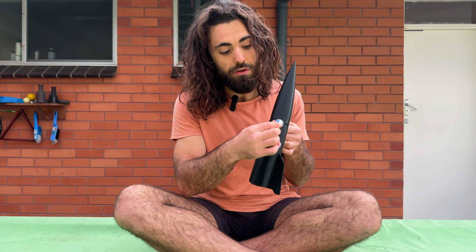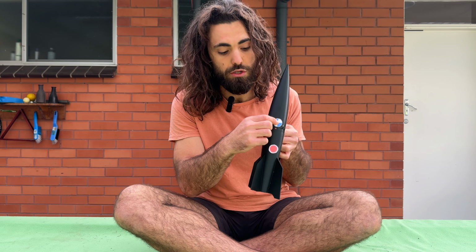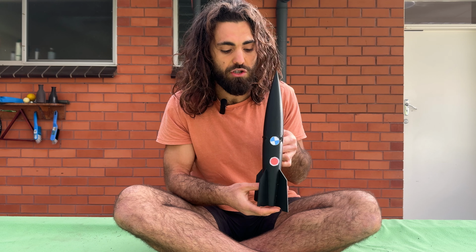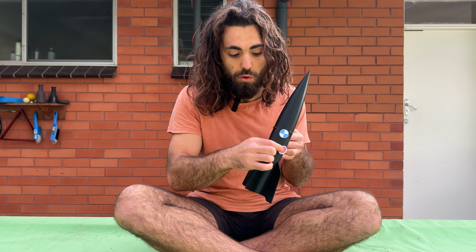One thing we should note here is that both of these points aren't fixed. As the propellant gets shot out, you can imagine that the center of gravity is actually going to shift forwards because we're losing all the mass of propellant down the bottom. As the rocket actually tilts, because the center of pressure is dependent on how the rocket's actually hitting the airflow, this point is also going to move around.